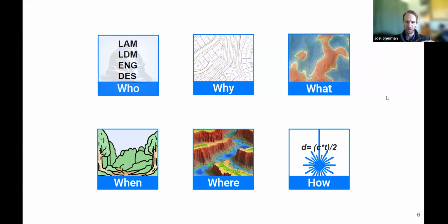It'll give you a much better representation of what that earthen surface looks like over space, specifically within these highly topographic areas. Within fairly flat areas, it's not necessary, but I think it does improve the accuracy of the data set you're working with for original grade, because there are so many more points, so many more measurements. But it might not be necessary if you're working with a fairly flat or a flat site.